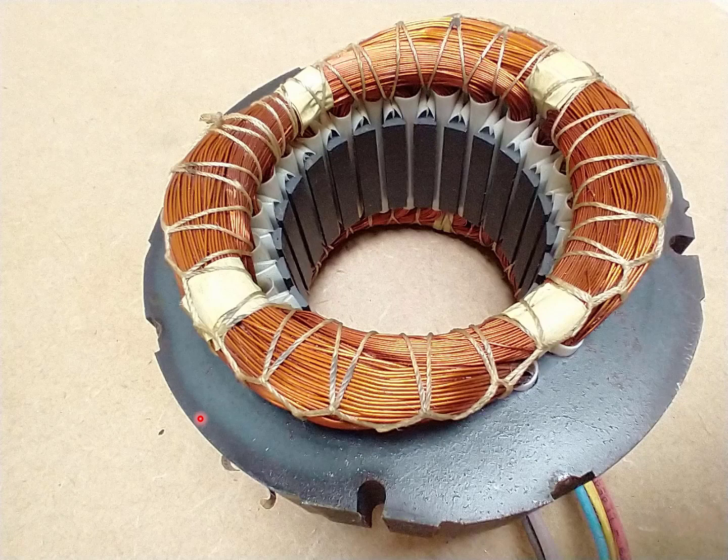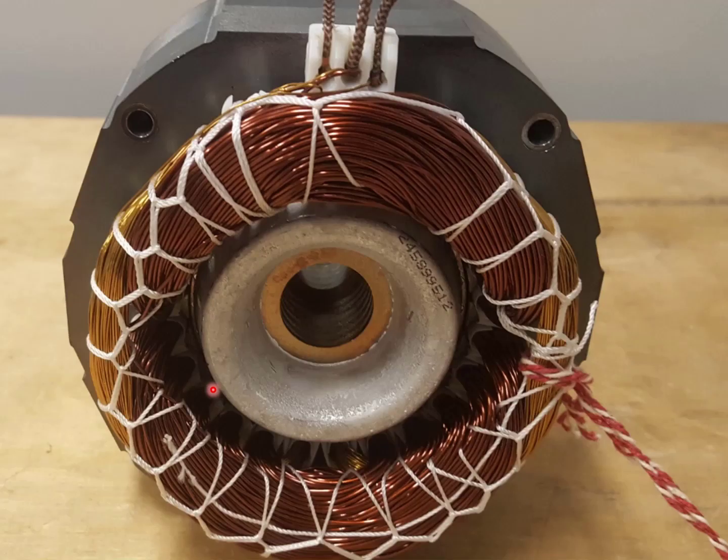Here's an example kindly provided by Motivity Limited in Galashiels, Scotland. We can see only the stator. It's a two-pole, single-phase capacitor motor. And here is another example, kindly supplied by MCC Sekop in Germany. It's a refrigerator compressor motor, again two-pole, capacitor start. And here we can see also the cage-type rotor with cast aluminium conductors. Although both these motors are single-phase motors, everything in this webinar relates to motors of any number of phases.